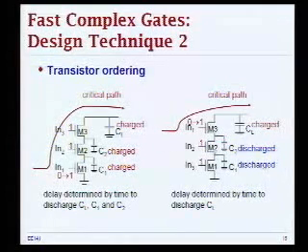You want to take advantage of these conditions on the other transistors. Let's say I have inputs 2 and 3 that are already settled to 1, and I'm just waiting for input 1 to discharge all of the capacitances. No, let's not do that. Let's do some work before that input arrives. If I reorder these transistors so that inputs already settled at 1 are in place, then I'm discharging C1 and C2 ahead of time.